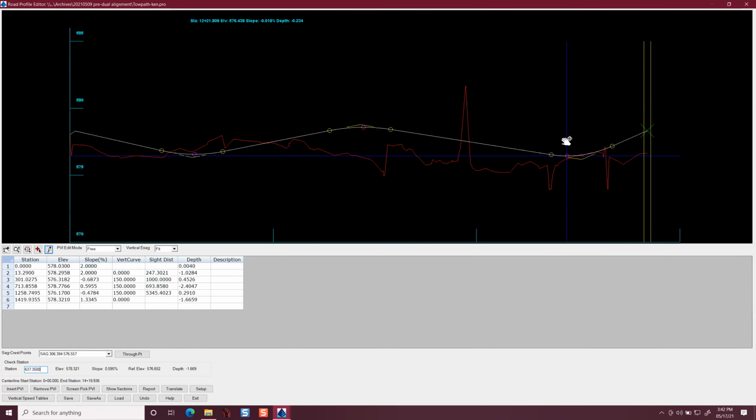Or you want it to just blend everything when it hits the intersection, like your choice of radial from curves. If you say radial from curves, it's going to set those triangles in like that, and then it's going to back out the side road's profile to follow those shifted blended triangles.